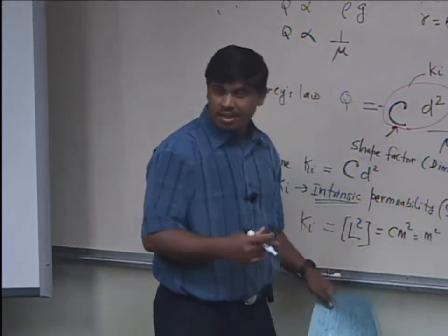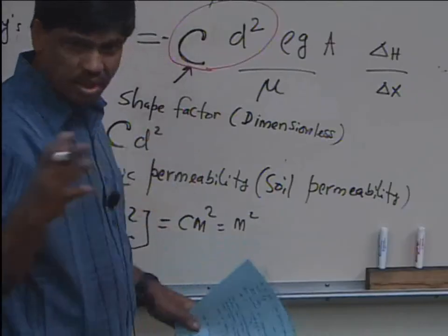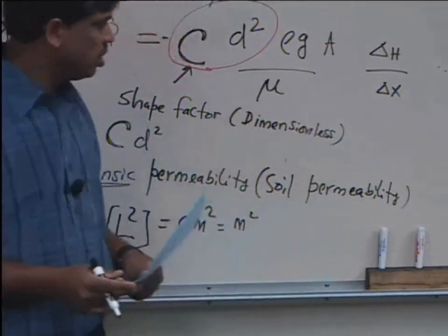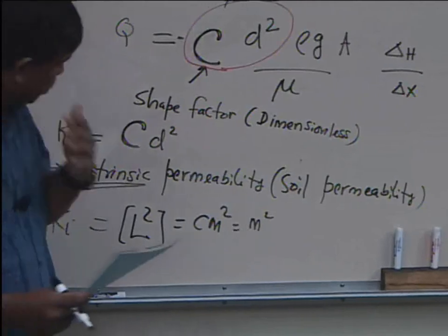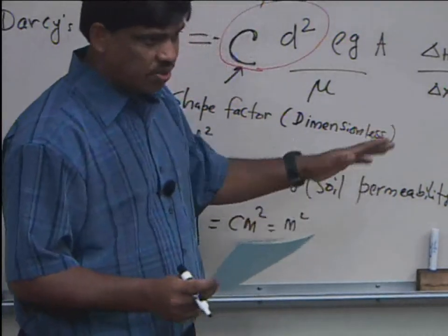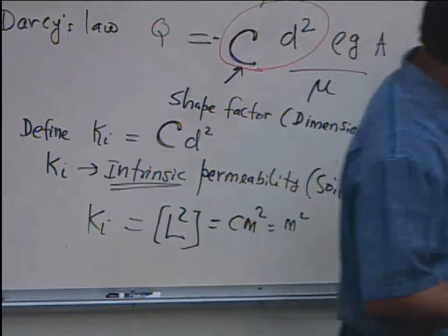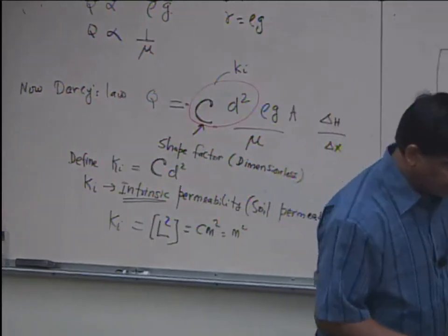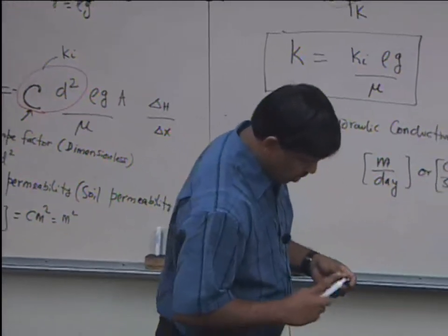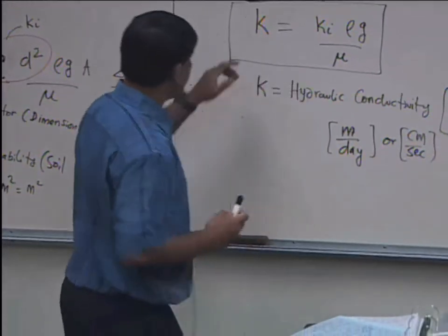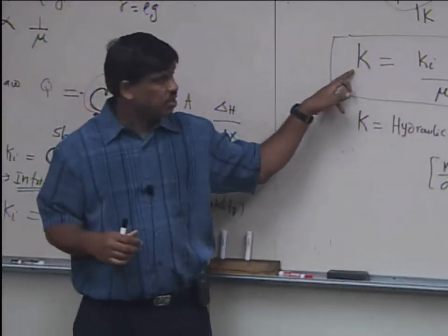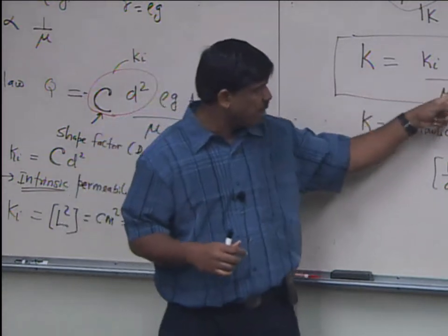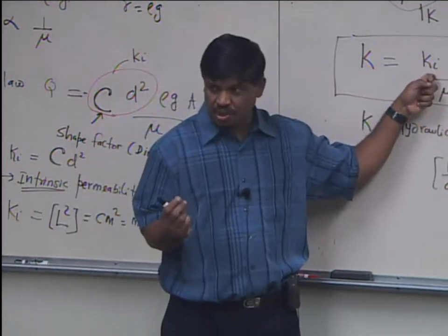And it's also called this Darcy, which I never use. I think the geotech literature uses this Darcy, which has got some weird definition. So I'm going to stay away from that unit, okay? So or feet, whatever you can use. Any length, and this is length per time. Okay. Now, what were we talking about? I was about to say something, I forgot. Okay. So anyway, the hydraulic conductivity is a property which is a function of the fluid property as well as the intrinsic property of the porous media.